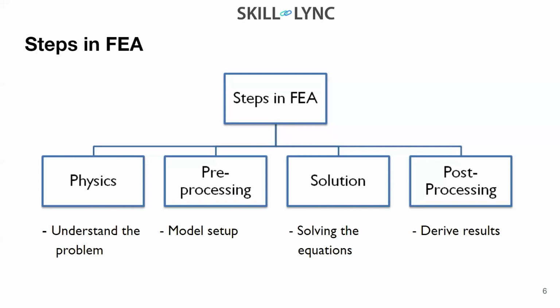Again, different problems will take different amounts of time, depending upon the sizes of the problems and the geometries which you are using. Okay, then again post processing. Post processing is again one of the important things. As I said, this is an approximate approach, right? The results you are getting need to be validated, right? If you are able to validate those results, then and only then will you be able to understand what the deviations are from the analytical and experimental approach, right? So those are the things.